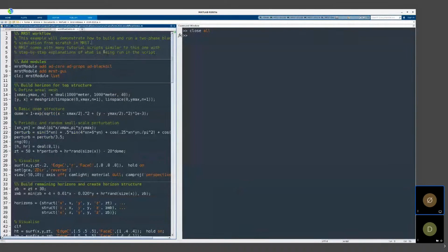For this example, if you're on Octave, there is a separate function called workflow demo underscore Octave, because part of this setup in the beginning will not run in Octave because we don't have support for a few things. For instance, some interpolation doesn't behave in the exact same way in MATLAB and Octave, and also some of the GUI functionalities that we're going to look at will not work properly. The important thing is that the simulator part with the nonlinear and linear solvers is going to work. So that's why I've saved the grid that we're going to use here and the rock into a mat file that you can load in Octave so that you can run the same example using workflow demo underscore Octave.